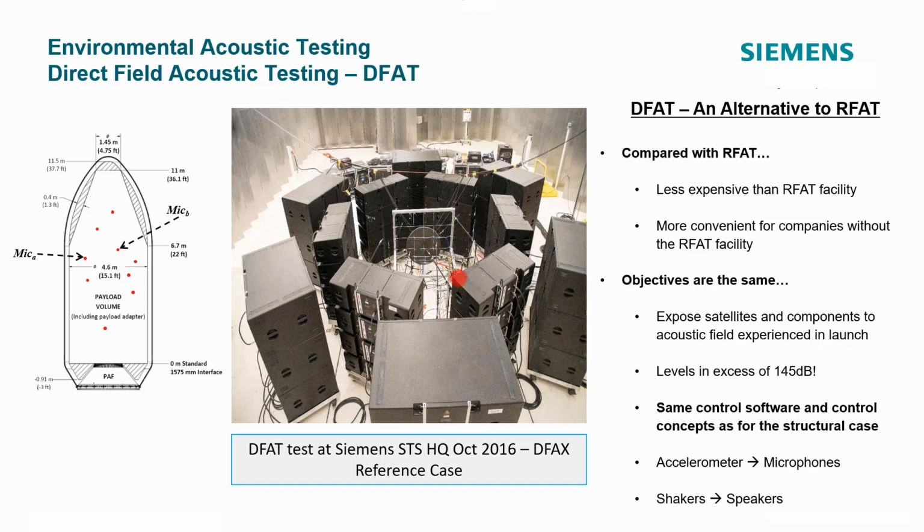But of course, you're going to be exposing these to some extremely loud levels. Again, you want to achieve that acoustic volume similar to what it would be exposed to in space during the launch. And these levels can be in excess of 145 decibels. So if you went and stood in here during a full level test, that would probably shake you to death and probably kill you. Those are extremely loud levels, but these components are exposed to those levels as they're launched into space.